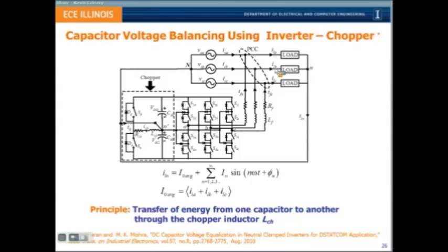The total voltage is always a constant, which is ensured because this inverter supplies only reactive power. It doesn't supply any active power. So there is no chance by which the capacitor voltage can discharge. It will remain constant because there is no active power drawn.